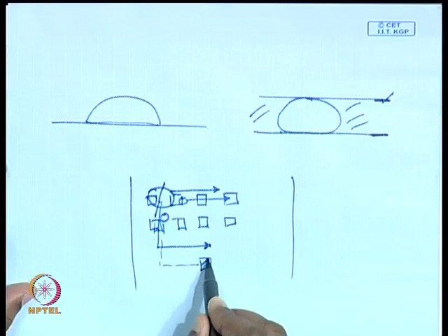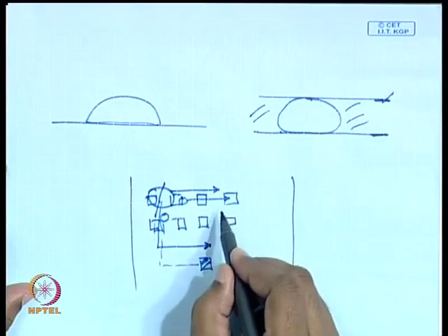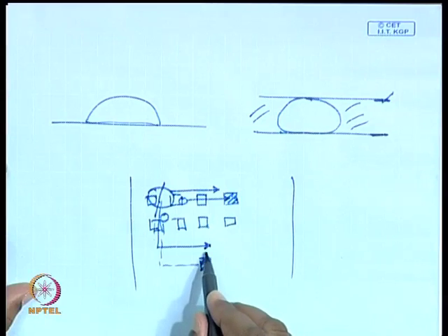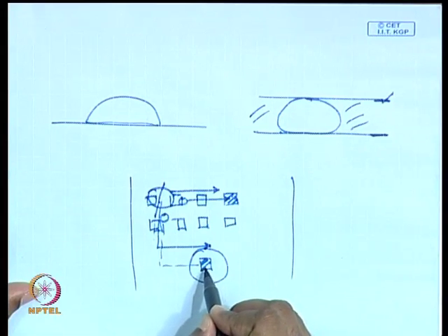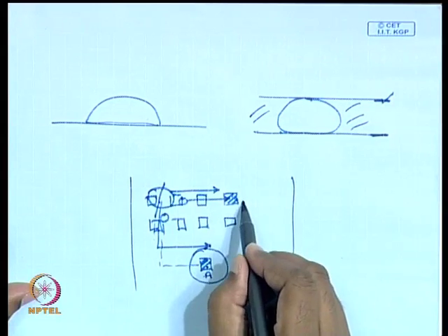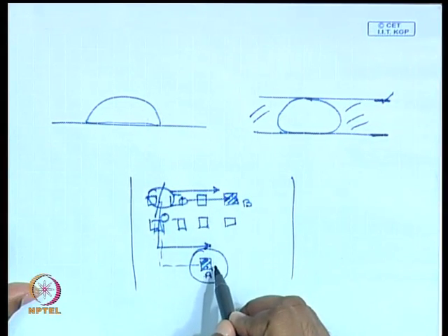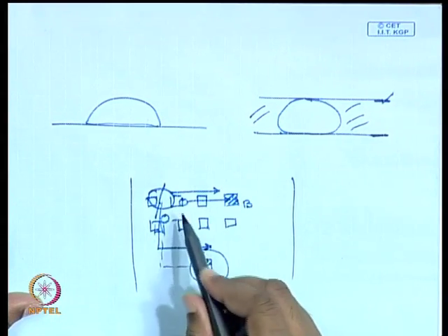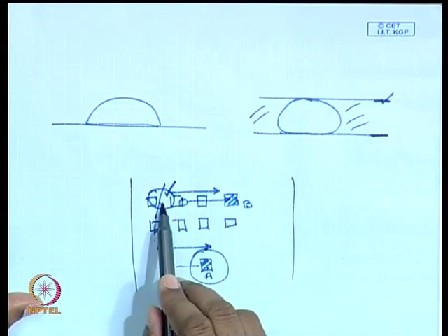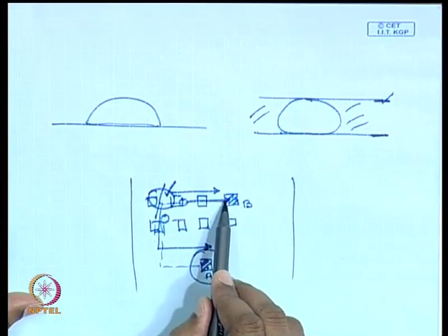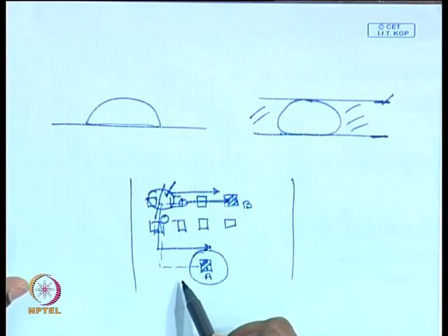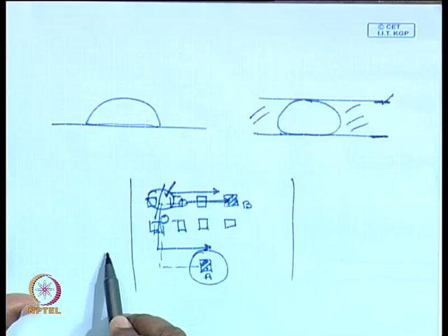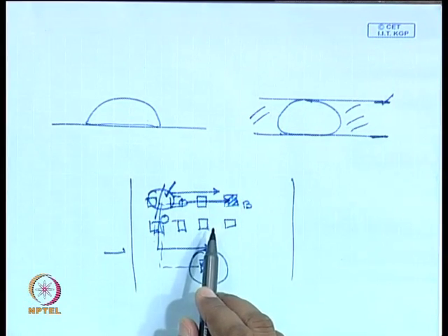So, you can have reagents parked on one of the electrodes over here and another electrode over here, and you can monitor some property, it could be fluorescence, of the droplet when it reacts with the reagent present in this electrode and in the other electrode. Thereby, you could monitor maybe the concentration of two species present in this droplet. So, the easy programmability of the entire two-dimensional electrode matrix gives enough flexibility to the system, which has a lot of potential for subsequent commercial use.